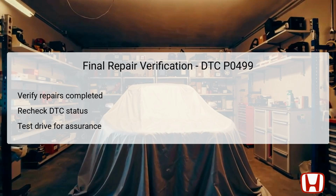After completing any necessary repairs associated with DTC P0499, it is essential to conduct a final repair verification. This process involves turning on the vehicle and rechecking the DTC status with the HDS to ensure the fault code has been cleared and does not return. A system or component that originally caused the error must now operate within normal parameters.